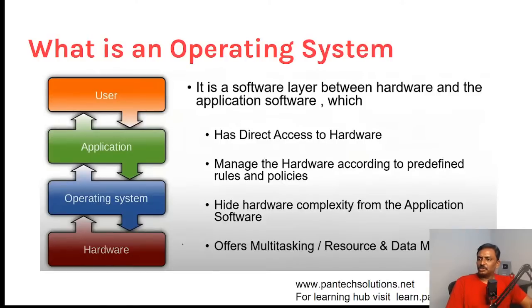Ashutosh Kumar asks about interfacing of HC05 and LoRa. See, LoRa modules are different. HC05 is a Bluetooth module. For the LoRa module, the communication medium is different. Sorry, the RF communication is different. The frequency is different. HC05 is a Bluetooth module, but the interface is the same. There are a lot of LoRa modules with SPI interface, and it also has UART interface. You could choose that one.